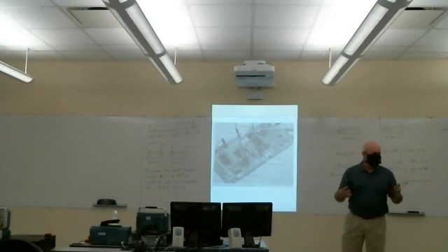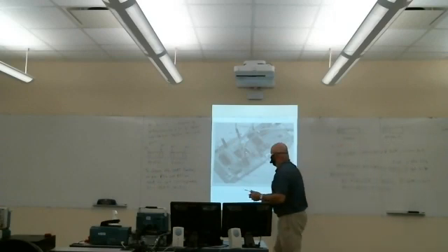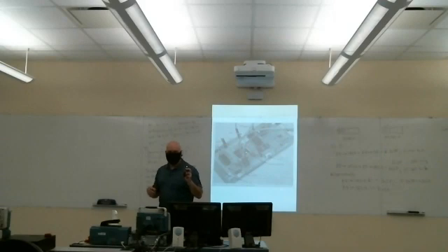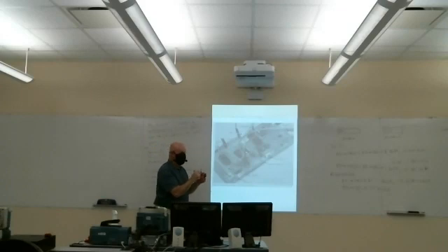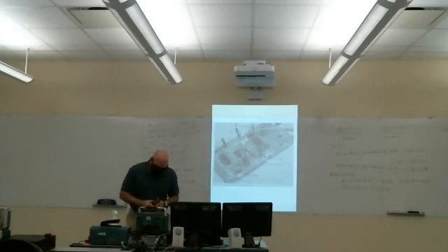a motor, a solenoid. So, of course, you have to know the mapping, not only the hardware mapping, but you can't just arbitrarily connect the device up to a pin without knowing what pin you're mapping to, because you've got to drive that pin in software. So you have to keep track of where you have your devices connected to.